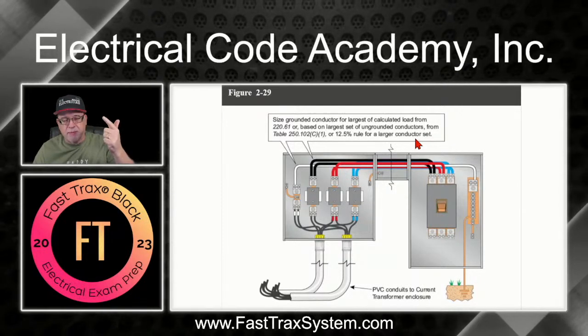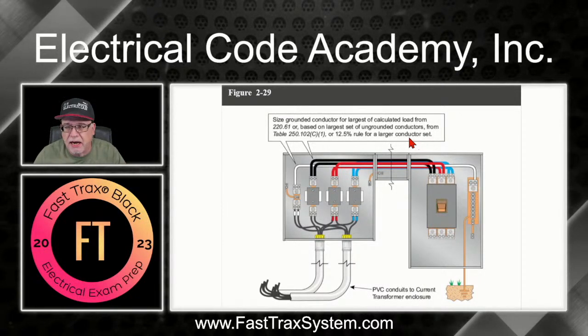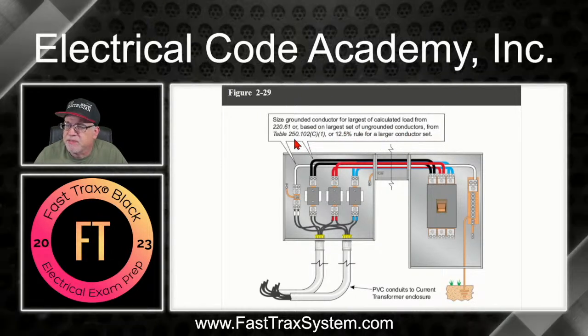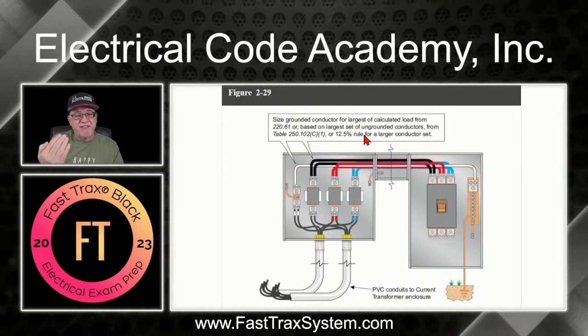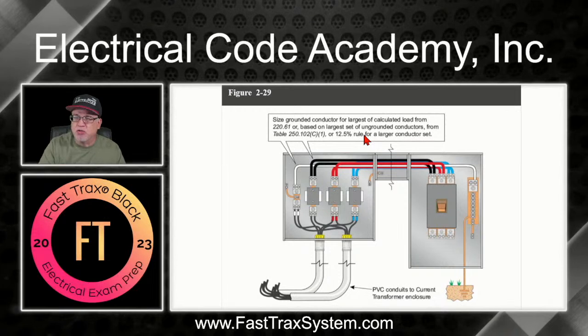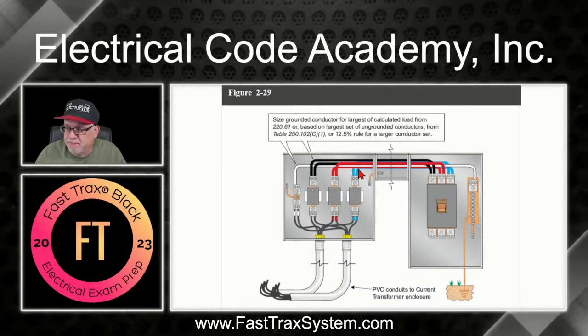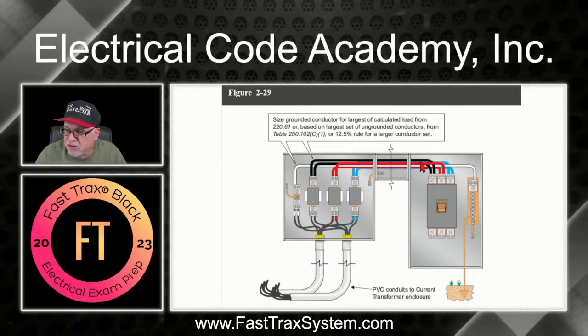We already, remember, I'm hammering that home. You have to do a load calc. Or it has to be based on the largest set of ungrounded conductors from Table 250.102(C)(1). And if it exceeds that value in the table, then you have to use what? 12.5%. And that's going to determine the size of this grounded conductor.